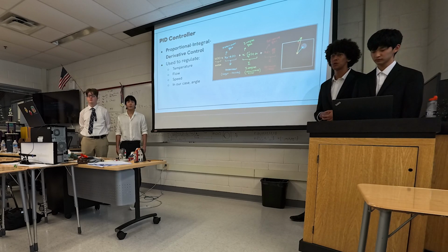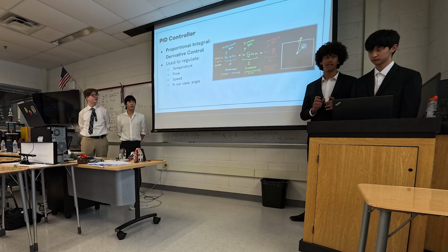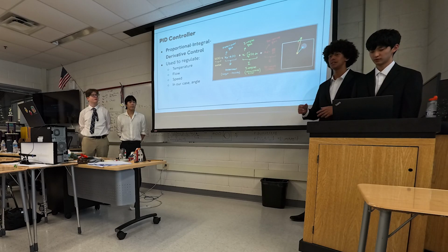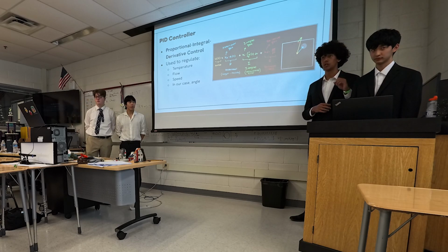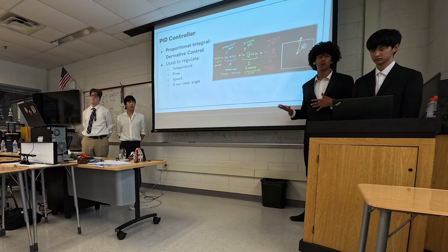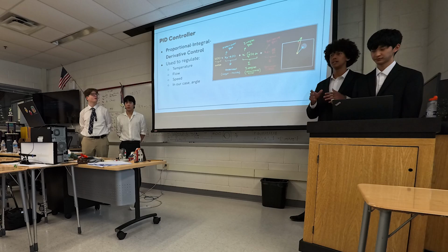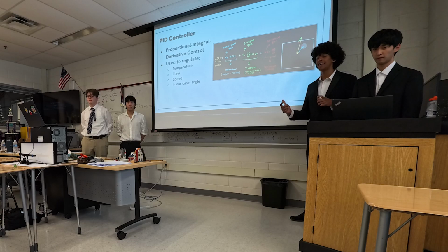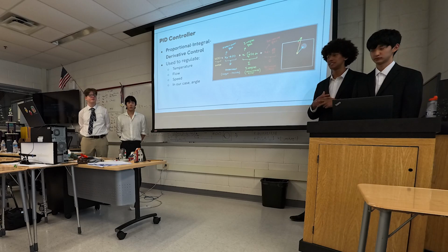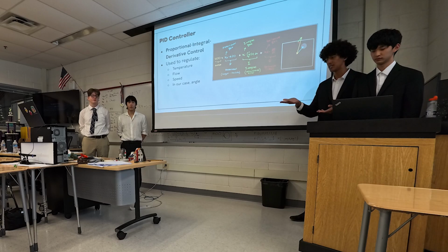The basics of how a PID controller works is, imagine you have an error function, which tells you how far the current system is from the desired system state. So in the case of the ball and beam, your error could be something like the current position of the ball minus the desired position of the ball, which tells you how far the ball currently is from where you want it to be, right? So if you sum scalar multiples of the current error, the integral of the error, and the derivative of the error, and head in the opposite direction, what you're effectively doing is counteracting the accumulated error in the system in order to shift the system closer to the desired system state, which in the case of the ball and beam is, again, the ball in its desired position with the beam flat.